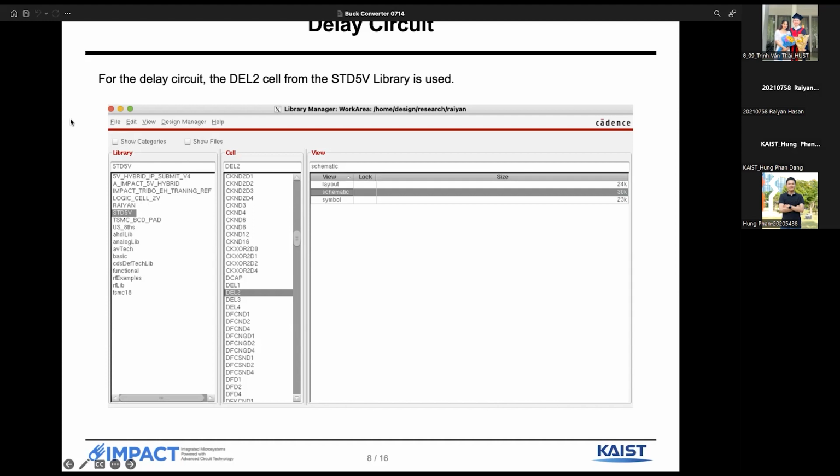Actually, I already made this when you sent that mail. Actually, we work with 5 volt because 2 volt is just over the limit. It can change the logic of the 5 volt voltage. If your VDD is only 1 volt, you cannot turn on the 5 volt MOSFET, I think, because you know threshold voltage, right? To turn on and turn off a MOSFET, you have a threshold voltage.